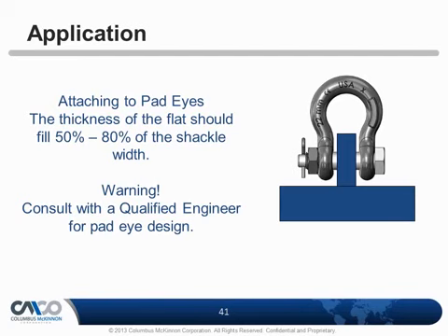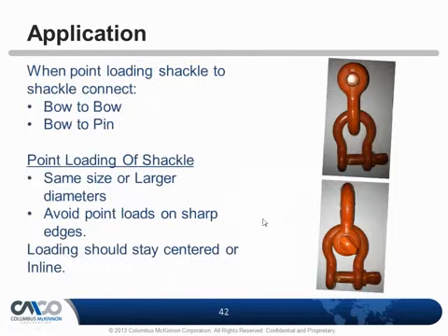So why would you spend all that money on the quality equipment that you have to lift safely, and then you're really not going to worry about the lift point that you're lifting from? And that's common, and it's just kind of a backwards type of thinking. It will always be your weakest point in the lift that's going to fail. And lift points are one, so you always want an engineer to design a lift point. And right now, there really isn't any standard on lift points other than get somebody that's qualified that can calculate the shear strength of that steel.